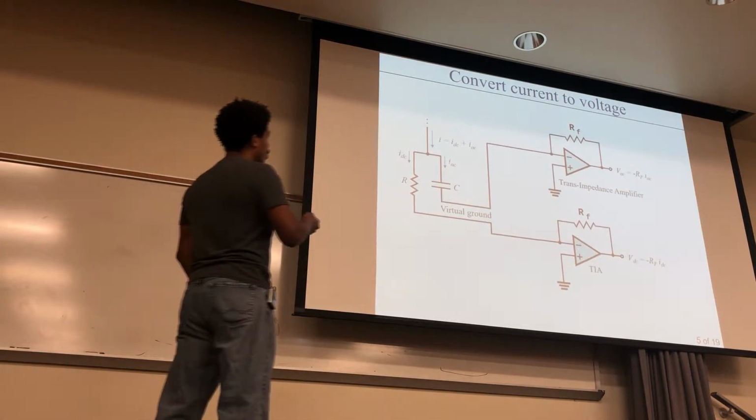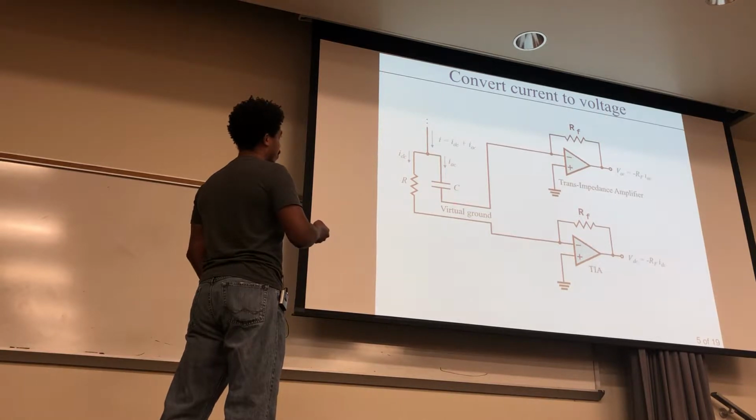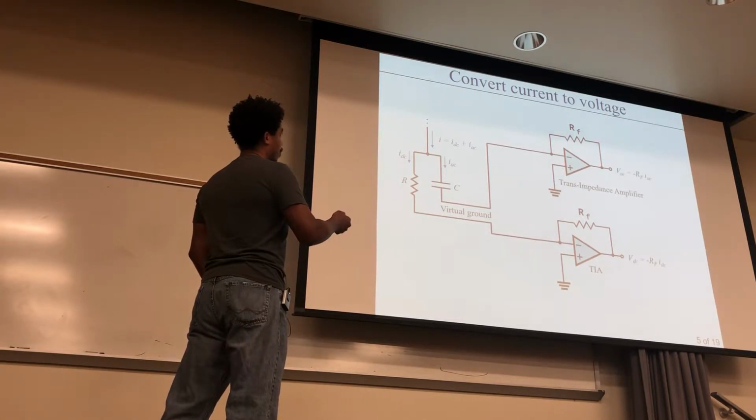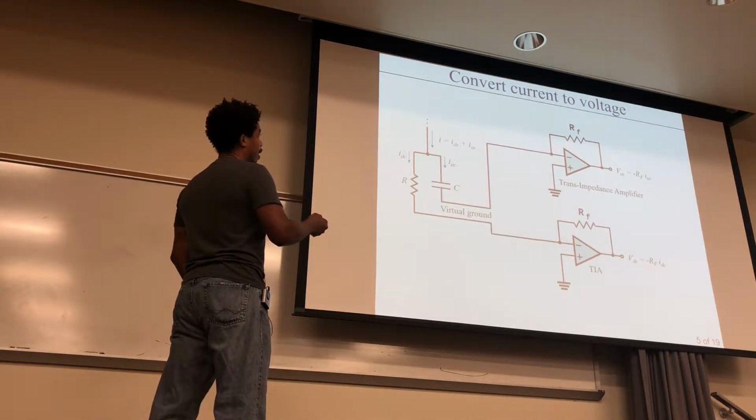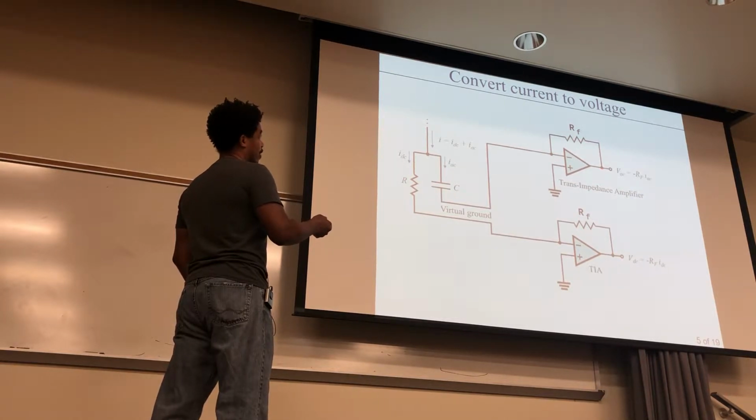But once the current goes through here, this AC signal that's going back and forth is going to go back and forth through this feedback resistor, and if that's grounded, if that's 0 volts, then if it's going this direction, this voltage is going to be right here. So you have your voltage, but it's your AC voltage, and it's proportional to this current right here. If the current is going this direction, then the voltage is less than 0 volts. But it's sinusoidal, so once your current starts going this direction, then this voltage over here is higher than that 0.